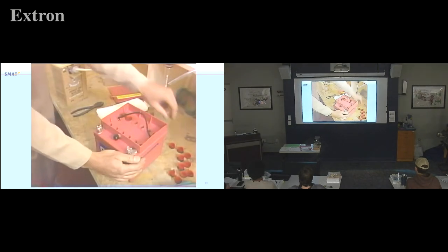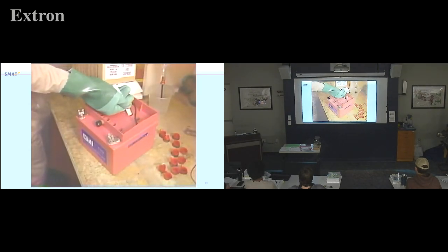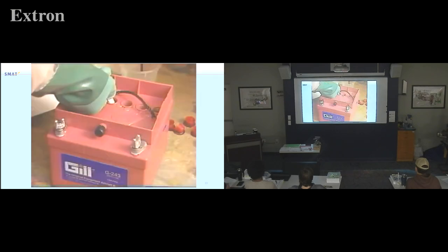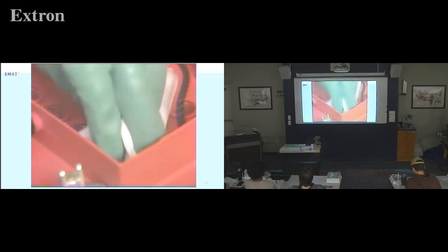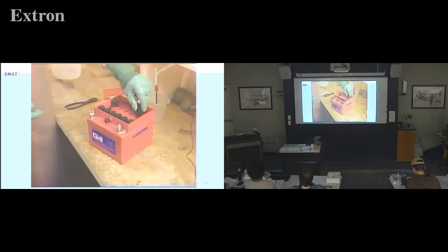Remove the storage seals. Then add enough electrolyte to each cell to just cover the separators. Be careful not to spill the liquid on the top of the battery. A film of electrolyte on the battery top can discharge the battery in a short period of time. Do not underestimate the importance of keeping the top of the battery clean.